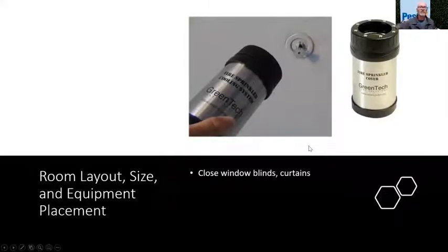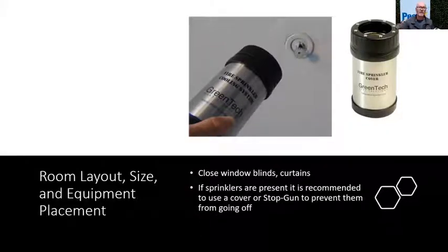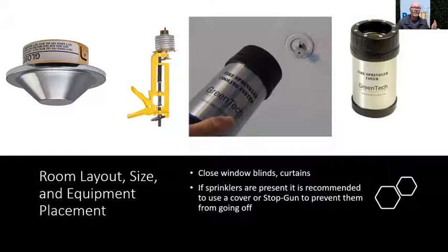One of the critical things, and I guess I look at this as what could really go wrong in a facility, is the issues associated with sprinklers. Sprinklers will damage your client's facility, it'll damage your heating equipment, and also probably have the fire brigade there. So all of those three will add cost to your project. The first thing I'd be looking at in any hotel room will be sprinklers. Do I cover them? Do I have them isolated? What do I do? They're the sort of things that you would talk to your client about. There are simple covers, like on the right-hand side here, we've got a thing called the fire sprinkler cover that would have ice on the inside and magnets and would actually just attach to the sprinkler itself.